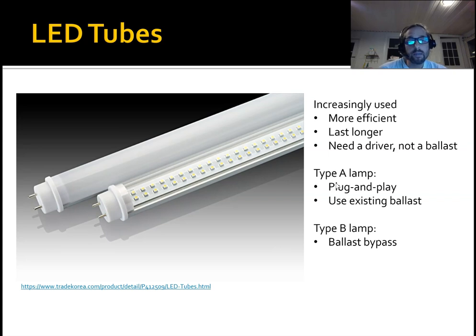Now remember that a fluorescent needs a ballast. Okay, so any fluorescent light needs a ballast. An LED tube, or any LED for that matter, needs a driver. Okay, so a driver, not a ballast. And this is an important consideration. If you have these plug-and-play LEDs where you just pop out the fluorescent, pop in the LED, that means that the electricity is still flowing through that ballast, right?